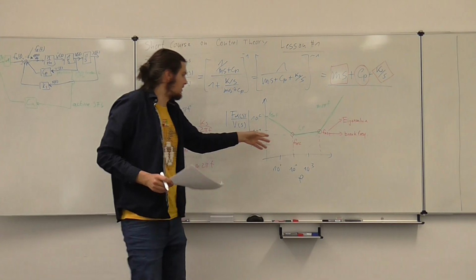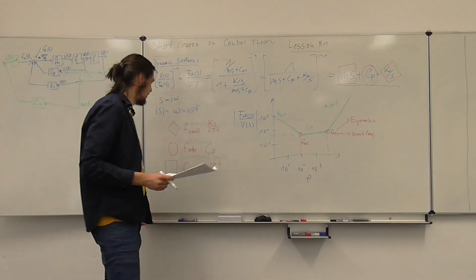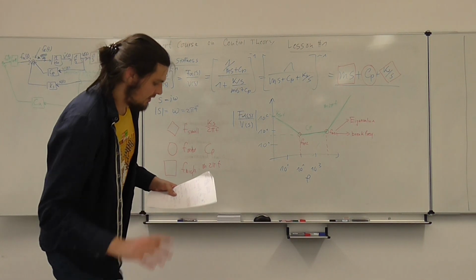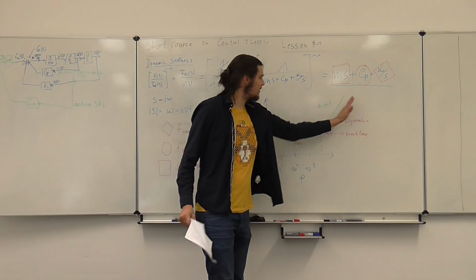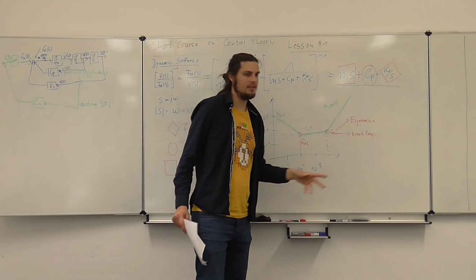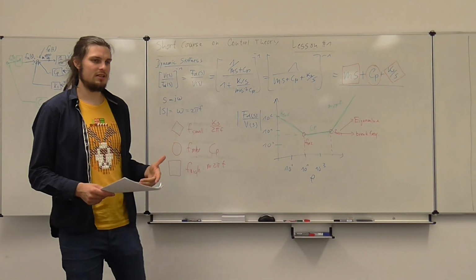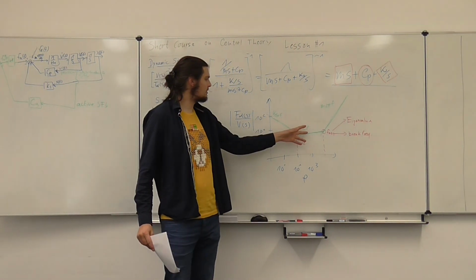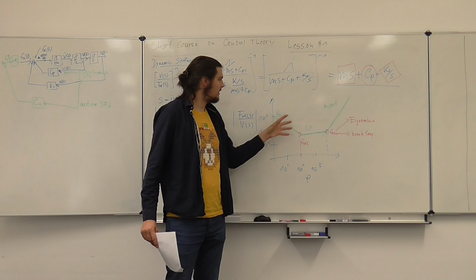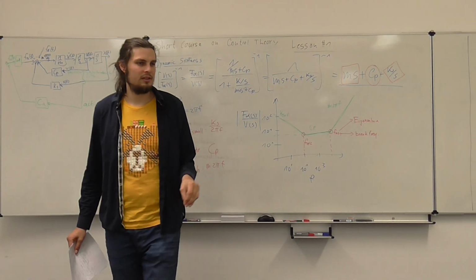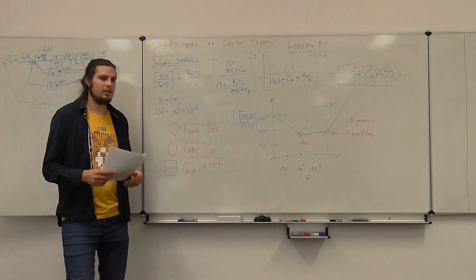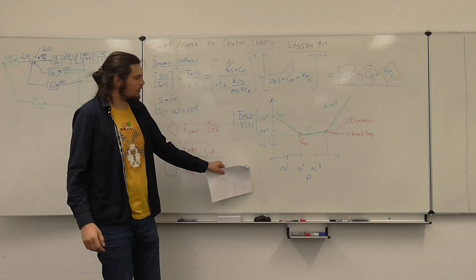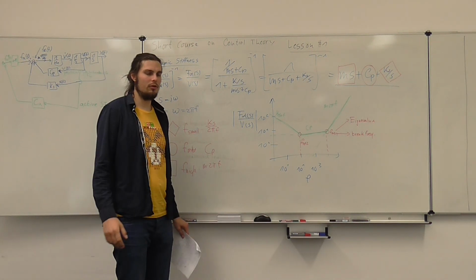Okay, so we have these here, and we will see that it's really easy to calculate them. But first of all, let's see if this makes sense to us. In this area here, the higher the frequency, the stiffer the system becomes because of the mass. Does that make sense? Come up with an example where the friction is almost zero, the stiffness is almost zero, and you only have this. Maybe just like a ship in the water. The ship is super, super heavy. But at very low frequencies, let's say DC, can you move a ship although it's super heavy?